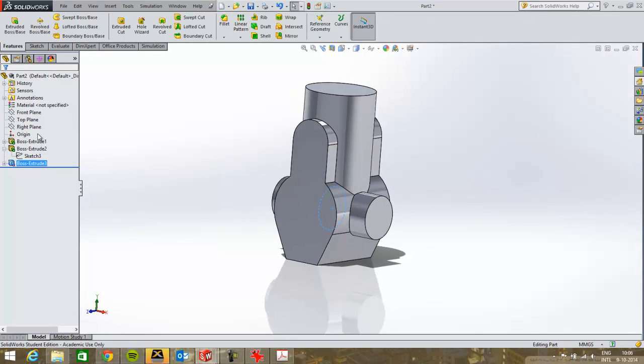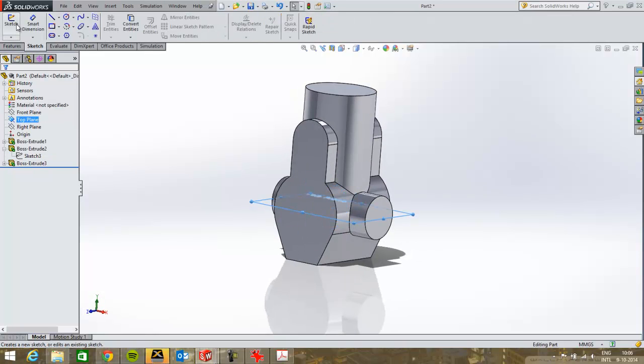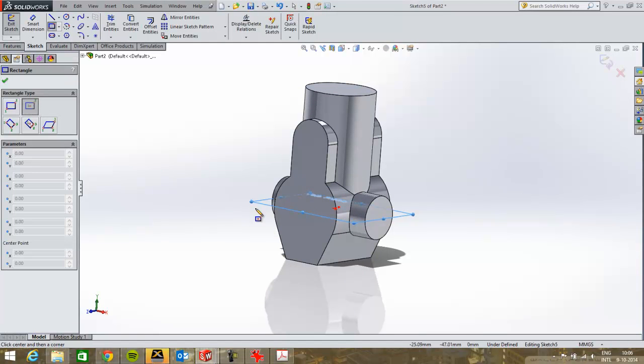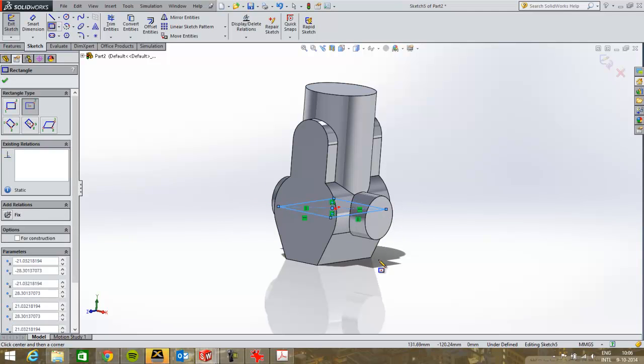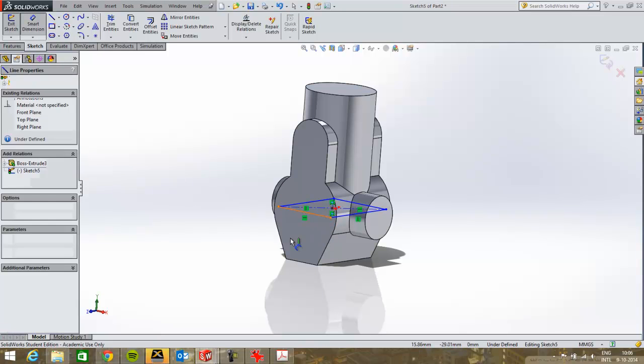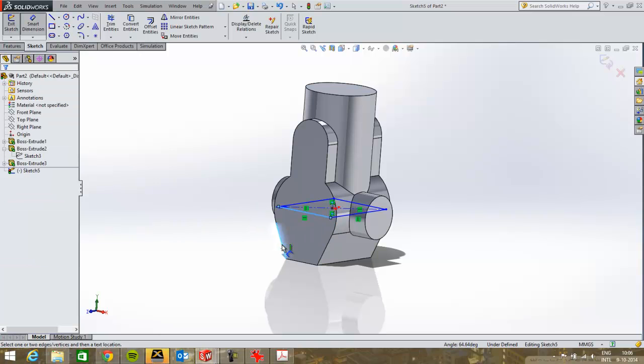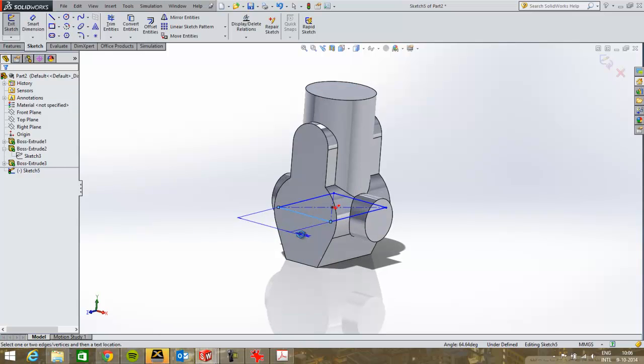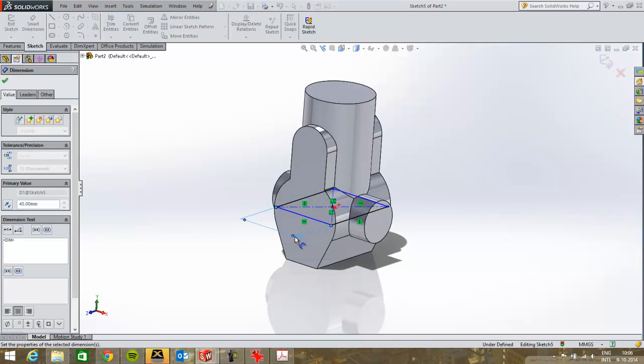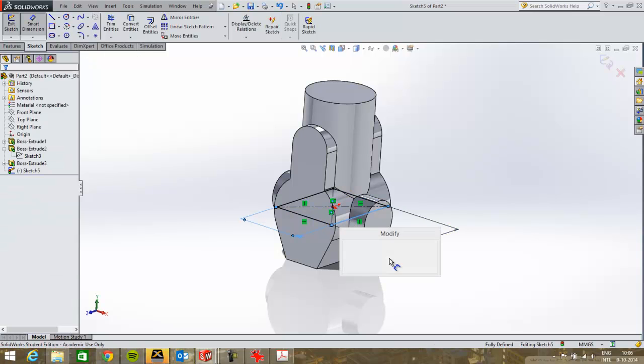And then on the top plane, I'll have to model a rectangle, and again, when your origin is at the correct place, it's really easy to use that. And the dimensions of the rectangle should be a width of 45, if I see it correctly. This value should be 45 according to the drawing. Let me see, 45. And then the thickness of this should be 24.